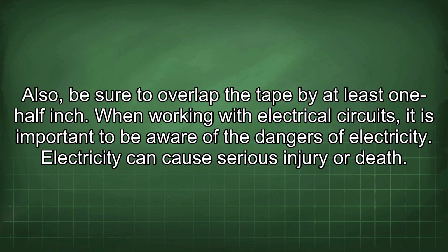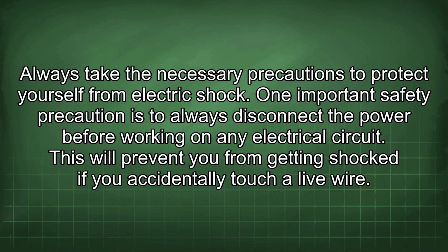When working with electrical circuits, it is important to be aware of the dangers of electricity. Electricity can cause serious injury or death. Always take the necessary precautions to protect yourself from electric shock. One important safety precaution is to always disconnect the power before working on any electrical circuit. This will prevent you from getting shocked if you accidentally touch a live wire.